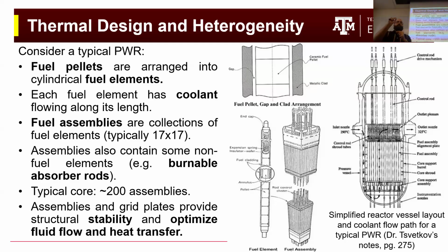So it's like you had a piece of metal inside of your fuel that has fissioned, and now you have these gaseous things building up inside of the fuel itself. Both because of heat and thermal expansion, it's going to expand, but also because of the swelling as the fuel is burned up, we keep that gap in there to reduce the pellet-clad interaction. So that's why there's the gap.